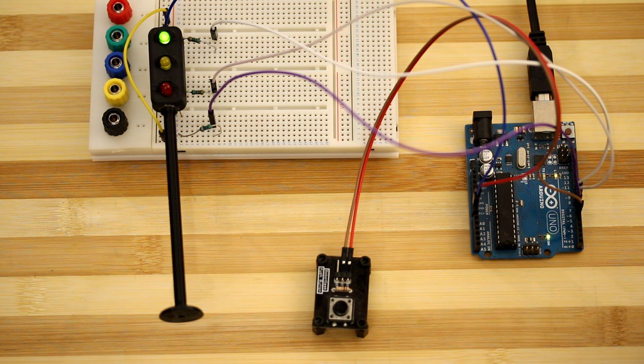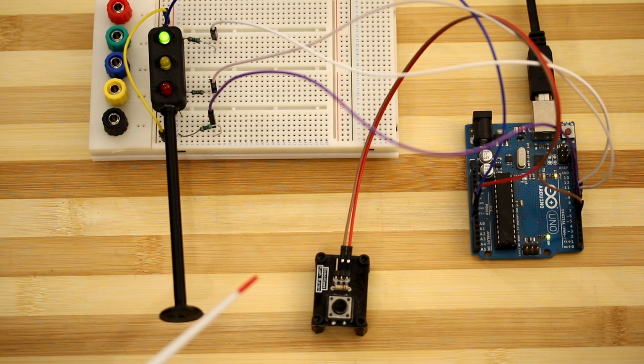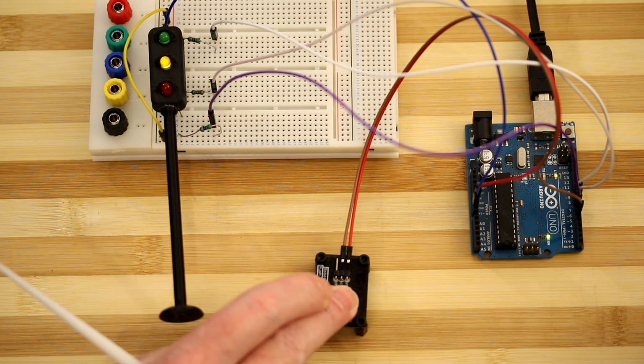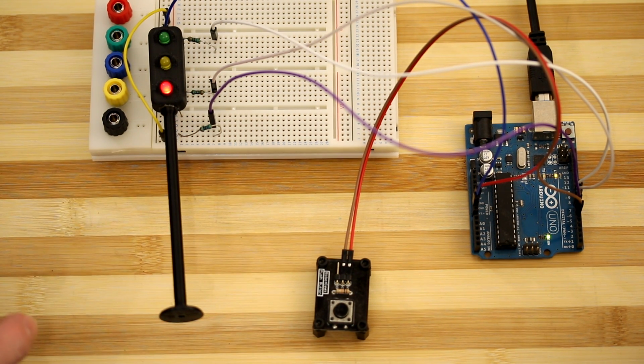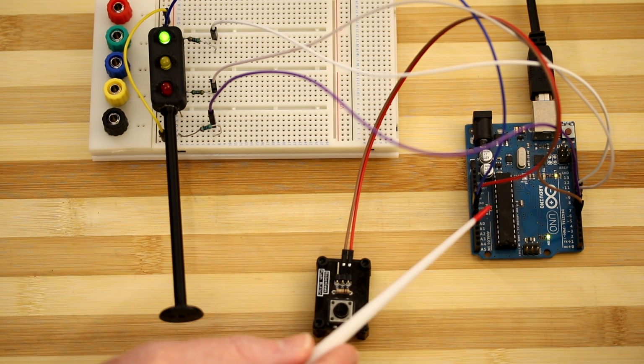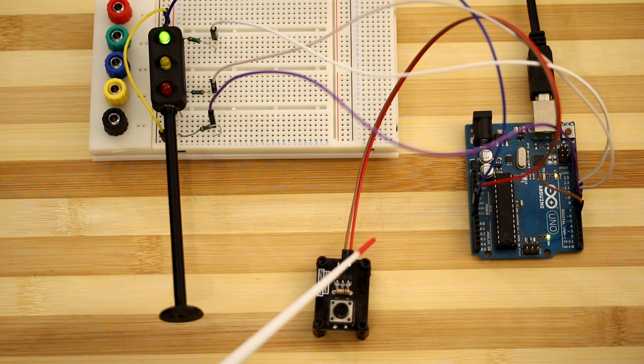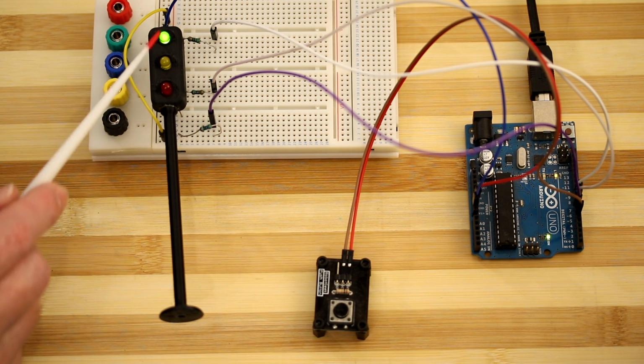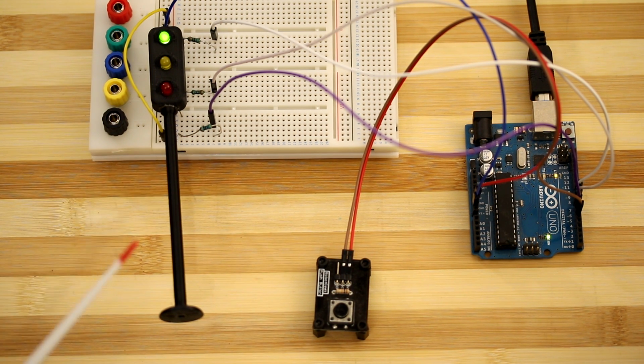Now at this stage, the aim of this video is to talk about adding a push button and wiring it into the Arduino. And then when that push button is pushed, calling a subroutine which changes these LEDs. So we're polling an input on the Arduino and then executing a subroutine to do this.